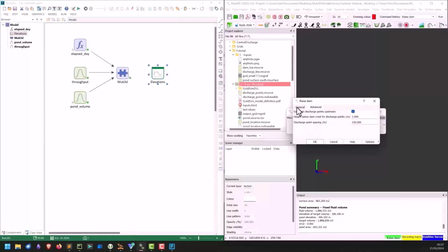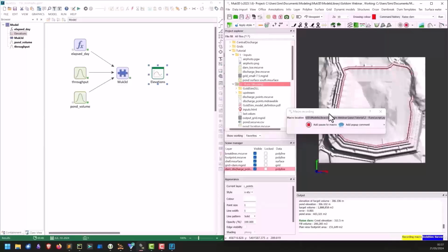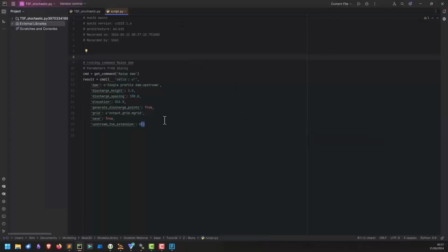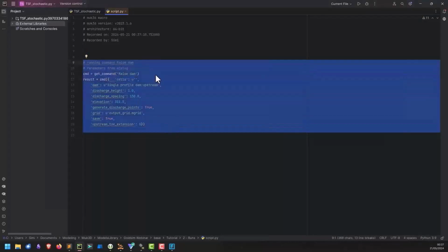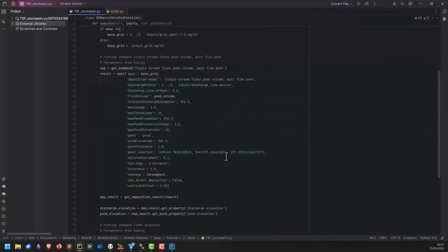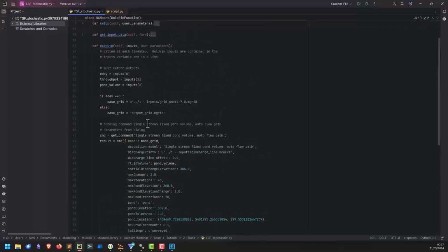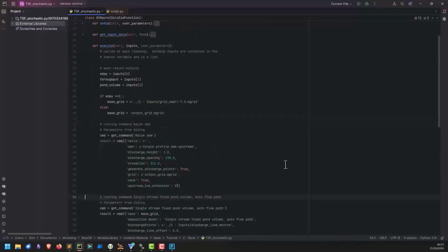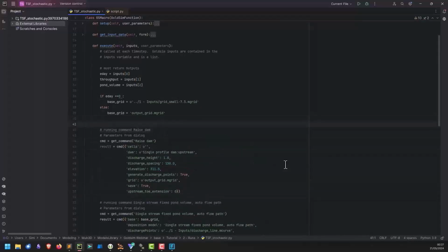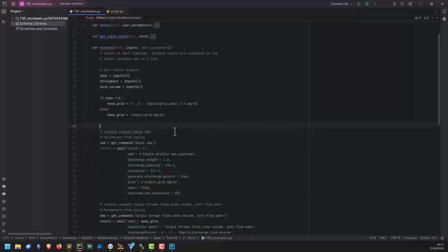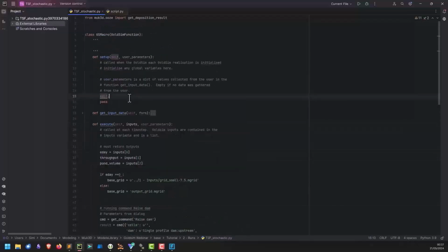As we're raising the dam, we'll build the dam wall on top of our tailings. Therefore, we need to calculate what the discharge elevation is. So that's it, we'll raise the dam. I will stop the macro. We've got that new command that appears to raise the dam. And so we'll copy it and bring it at the beginning, so that at the beginning of the run we assess: is there sufficient freeboard? And the freeboard we'll define just as the pond crest level minus the discharge elevation.